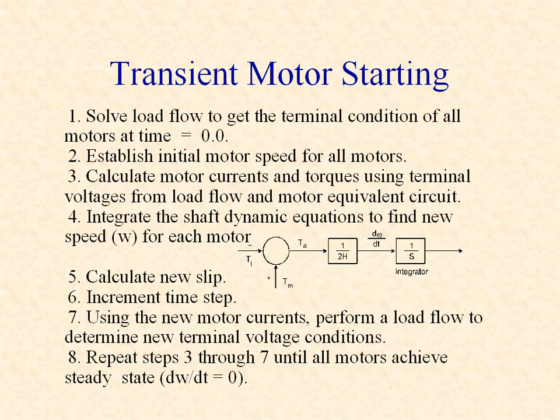The calculation methodology for transient motor starting is to solve an initial load flow to obtain the terminal conditions for each motor at time 0. Establish the initial motor speed for all motors.